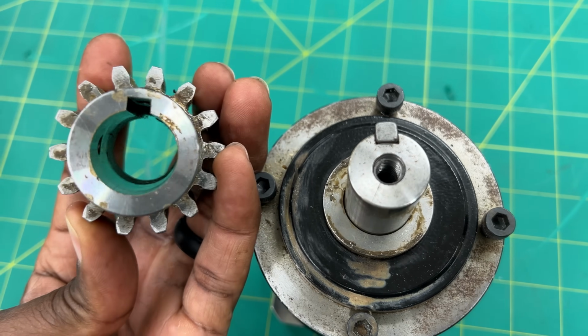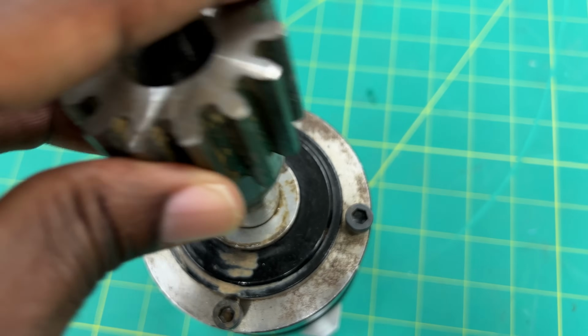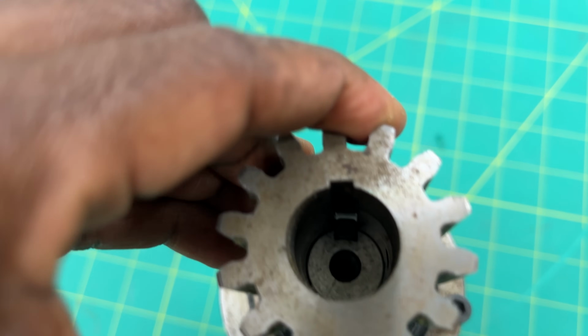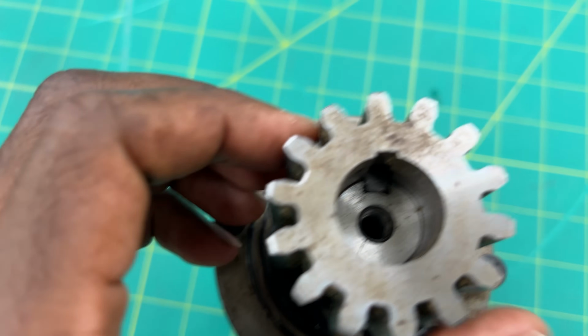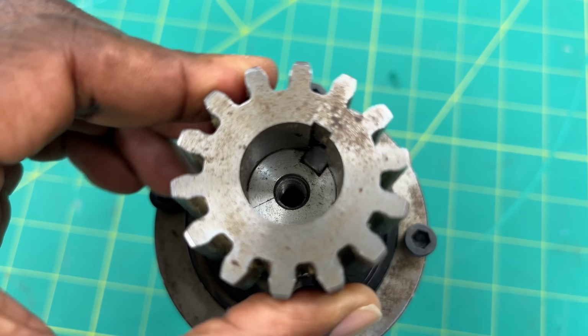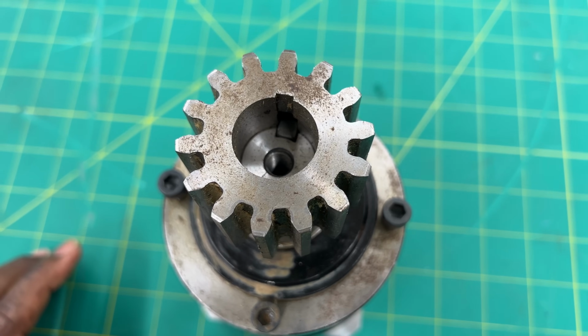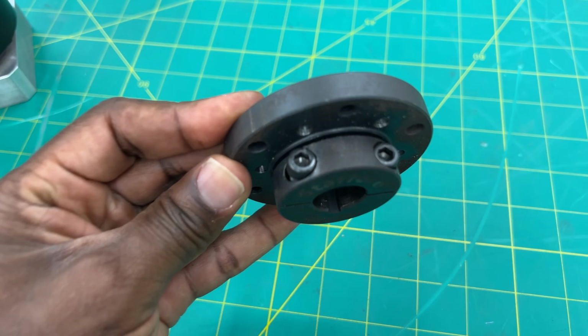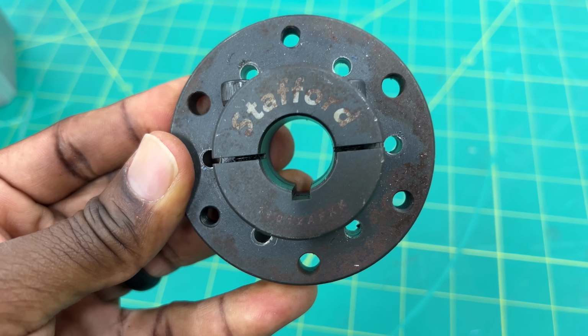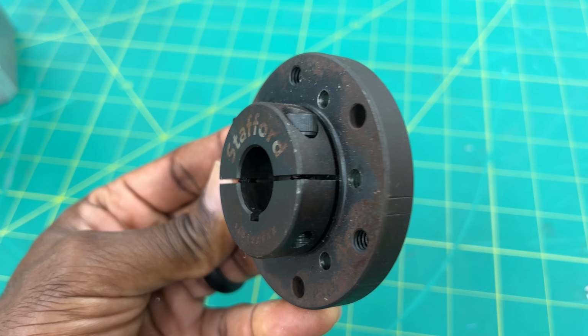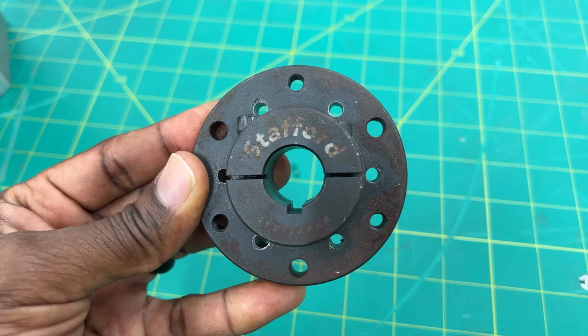You can use a key, which is really strong because you have literally put a blockage in between, and the strength of the material itself has to shear off. The key has to shear off in order to allow them to slip past each other. Sometimes you see both, where there's a key and a set screw. And then there are all sorts of other options. There are collars that are split with clamps so that as you use screws to tighten them down, it actually squeezes the shaft tighter and tighter with the clamp.